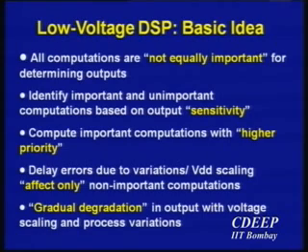What we really mean by that, from the communications point of view, is that people do unequal error protection, right? In the channel, when I send information, I sometimes do unequal error protection. Now, from the logic design point of view for DSP, from the design point of view, designing my logic, I'm going to do unequal error protection. Why? Because I'm trying to save power consumption. At the same time, I'm trying to also save area. So what's the best way I can scale my supply voltage down and still be able to maintain some sort of signal to noise ratio.